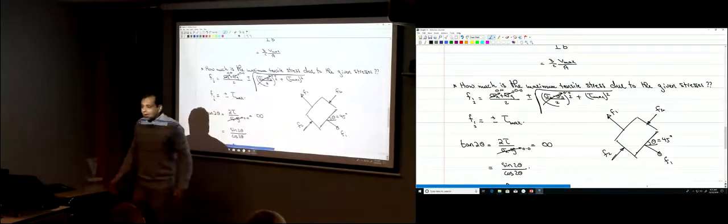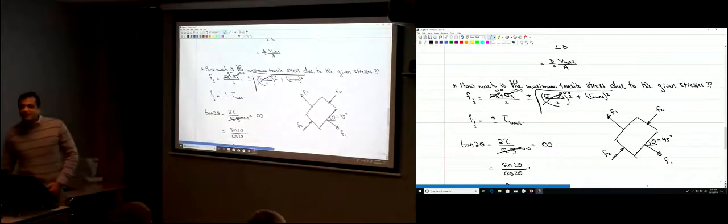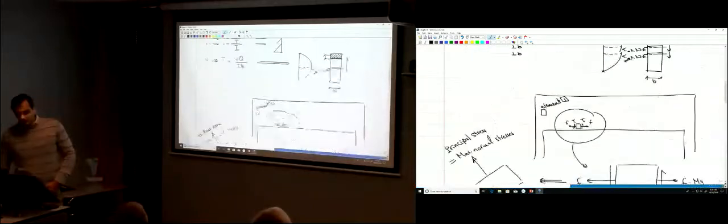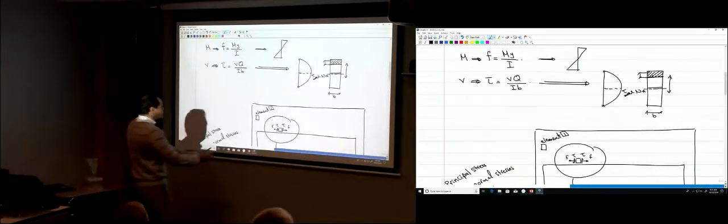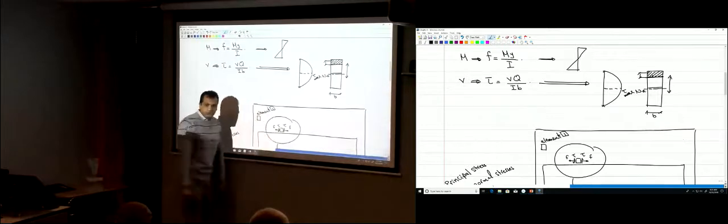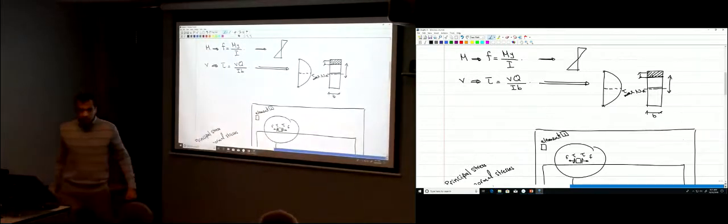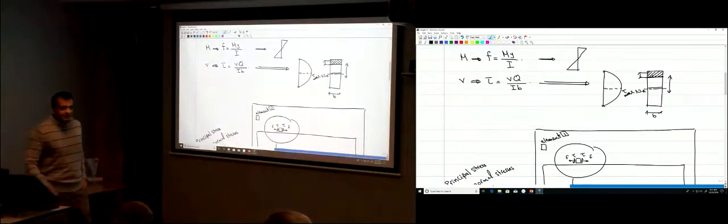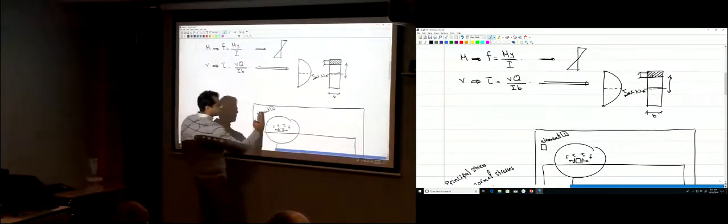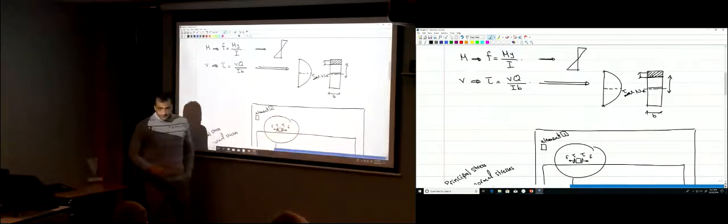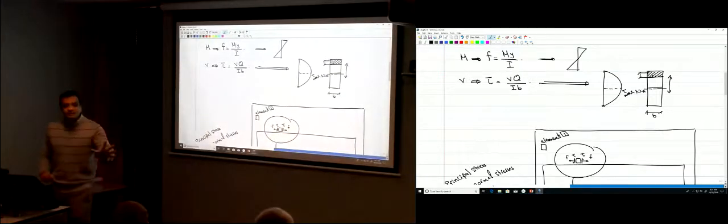So actually now, my problem is not having a shear force. In this beam, my problem is that there will be tension in this direction. There will be tension at an angle of 45 degrees. As the shear decreases when you go in this direction, this tensile force will still exist, but its value is going to decrease. So my problem is that tensile force.